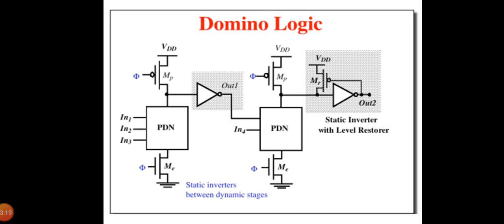And the second point is that very high speeds can be achieved with domino CMOS logic. Only a rising edge delay exists, while TPHL equals 0. The inverter can be sized to match the fan out, which is already much smaller than in the complementary static CMOS case, as only a single gate capacitance has to be accounted for per fan out gate.